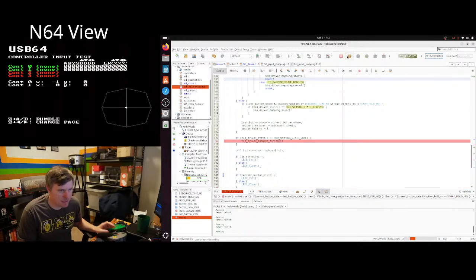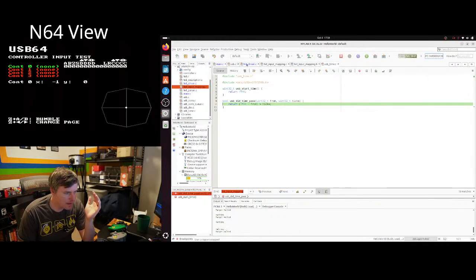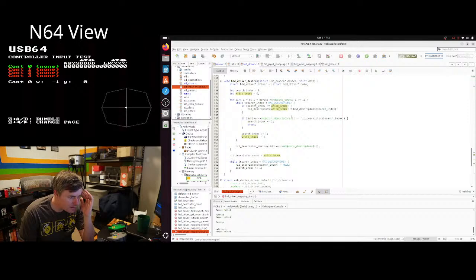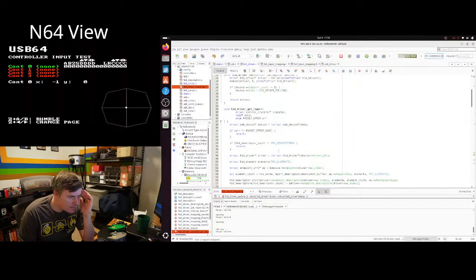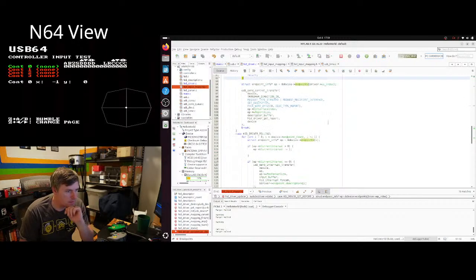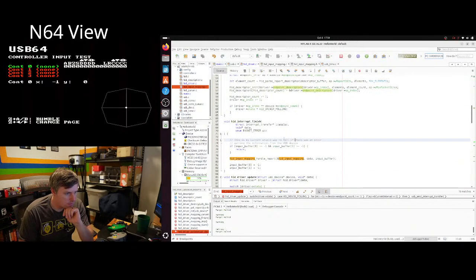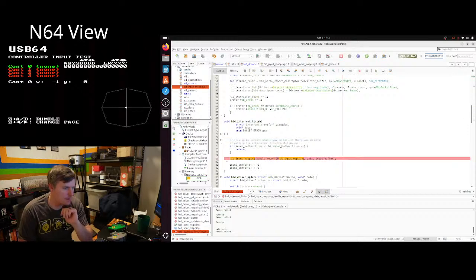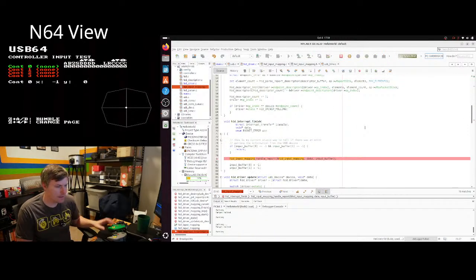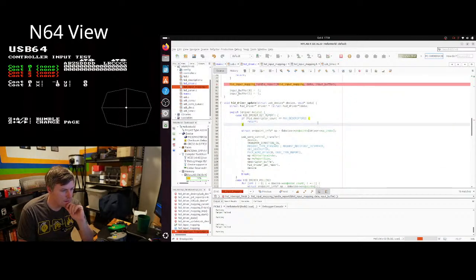What was I going to check? I wanted to check that it was going to get any input. So the HID driver on update, let's see. We should be polling. Okay, interrupt finish, handle report. So I'm just going to put a breakpoint here. This should be getting data constantly. And if it's not, then it didn't load the driver correctly.